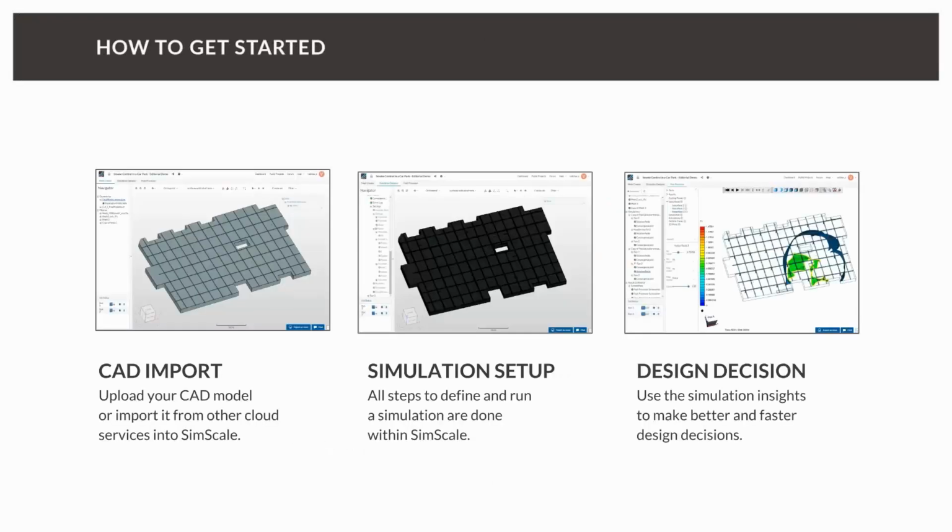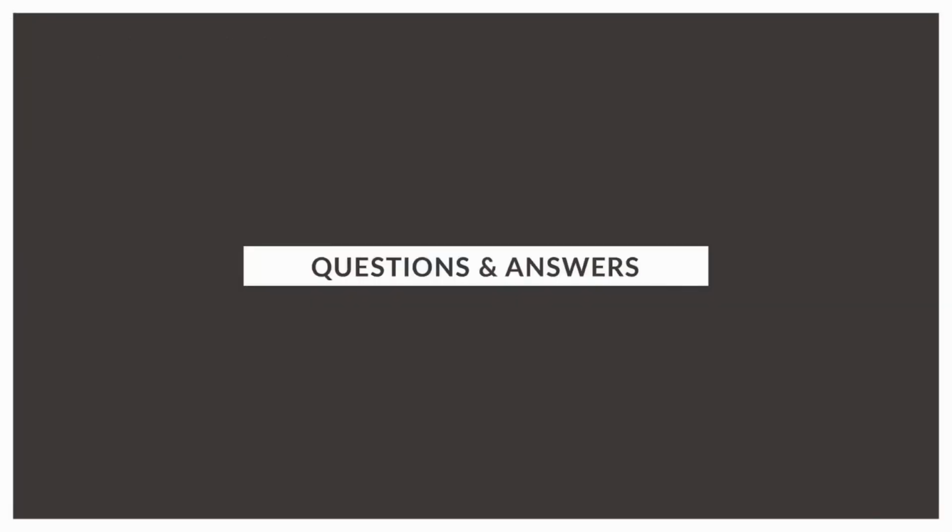Yes, and if you now get curious and want to get started yourself, there are just 3 steps you need to follow. First of all, you need to upload your own CAD model. Sometimes it's necessary to prepare these models for the meshing step, which I showed you, so you need to make sure mainly that it's watertight and closed. Then you can set up the whole simulation in your web browser and do the post-processing and the design decision based on the result evaluation, which can also be performed in the web browser.